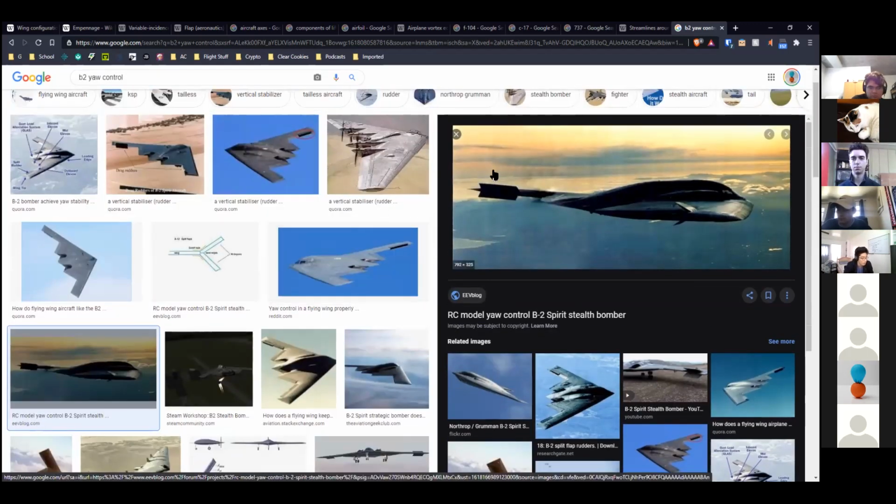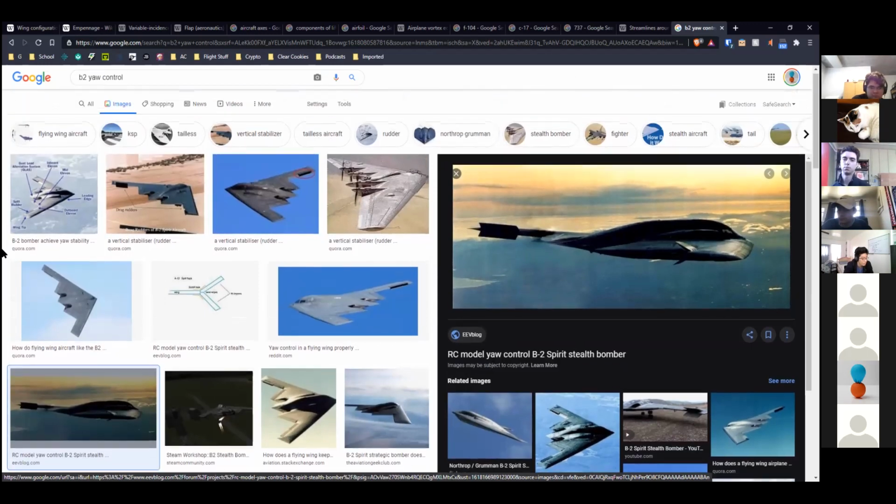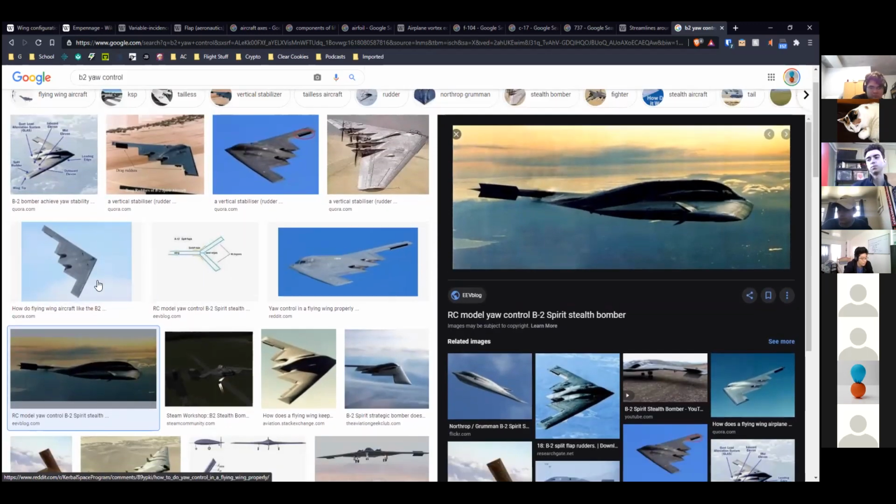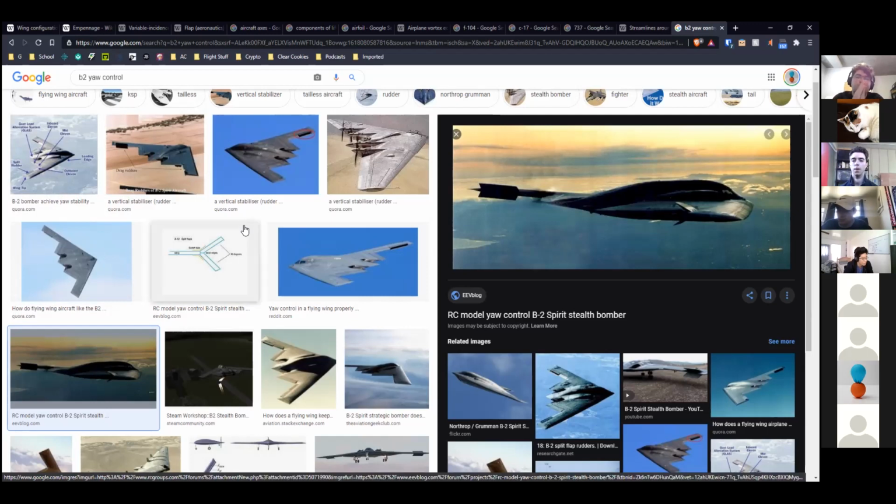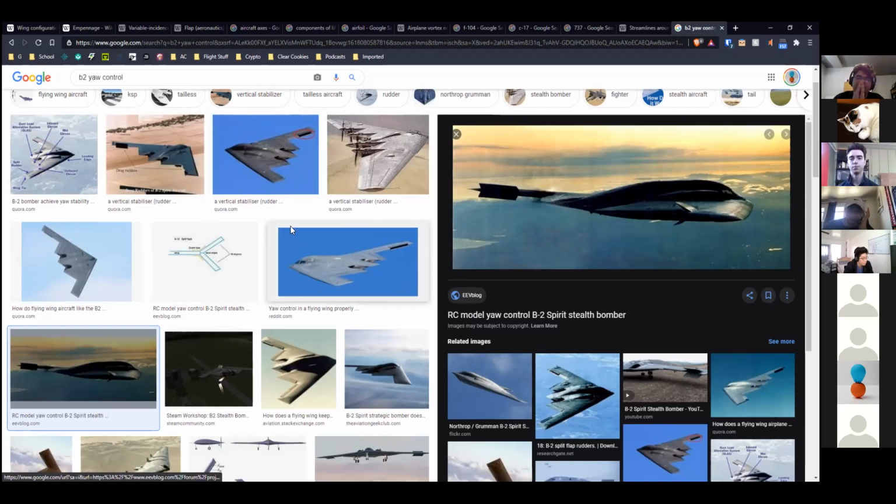In propeller driven aircraft, especially ones that only have single engines, you have to use the rudder to counteract that torque that I was talking about in the beginning. There are four separate things that change the overall torque on the aircraft trying to rotate it one way or the other, but you counteract that using the rudder.